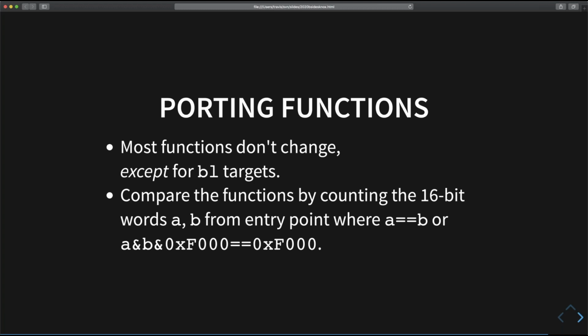So the way that I do this is that I realize that embedded developers usually use the same version of a compiler. They don't update their compiler frequently like a desktop Linux user might. And when you're using the same compiler to compile different versions of the same firmware, most of the functions don't change at all. And those that do change are usually for the small feature that gets fixed. They're not necessarily the same function that you might want to hook.